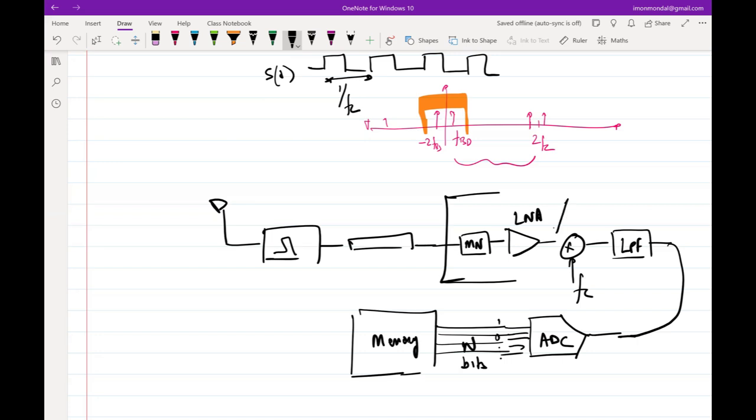Yes. Here, we assume there is only signal. Why can we assume that? Yes, we have already used one SAW filter upfront. But that's a good question. The reason it is good is because, as it turns out, the SAW filter cannot filter out everything very well. So the filtering is actually distributed. Now that becomes a system choice.